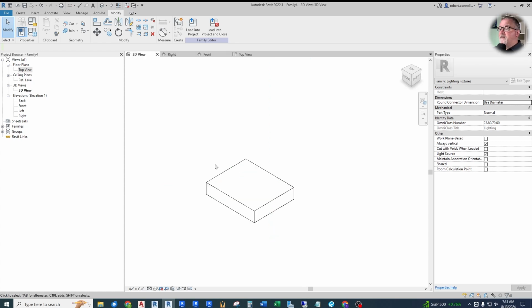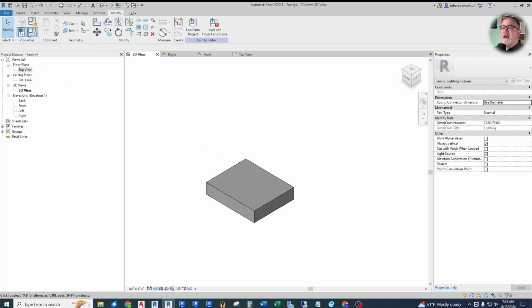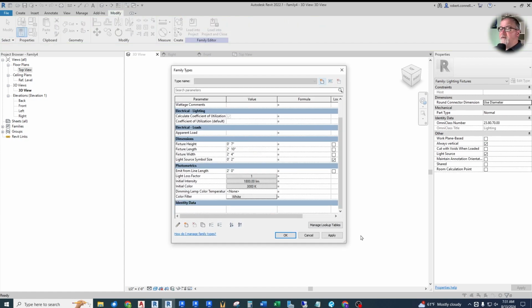So now we have our 3D view. Simple as that. We can change down here how it looks. Right now we're doing a hidden line. We can do shaded. And now's a good time that we can keep our architects somewhat happy by adding a material parameter to this extrusion. We need to apply a material parameter because there's no parameter in our model yet called material.